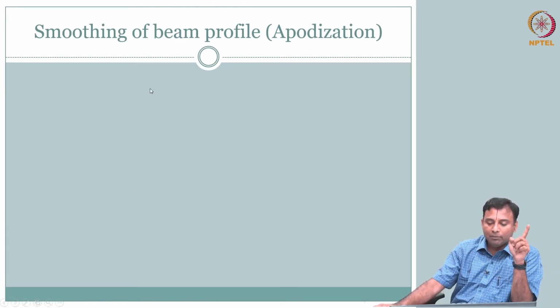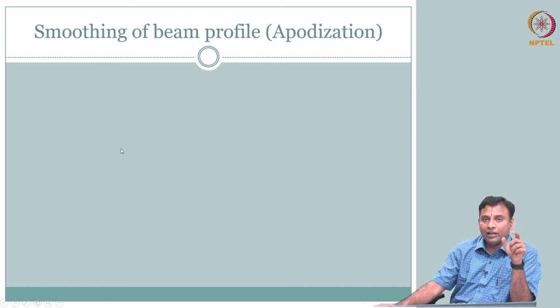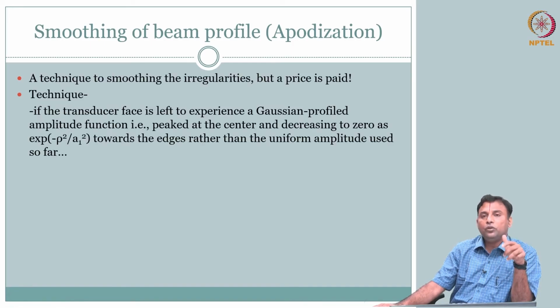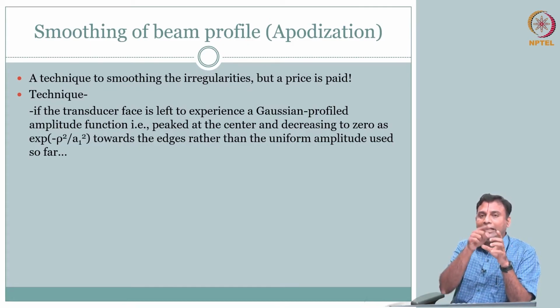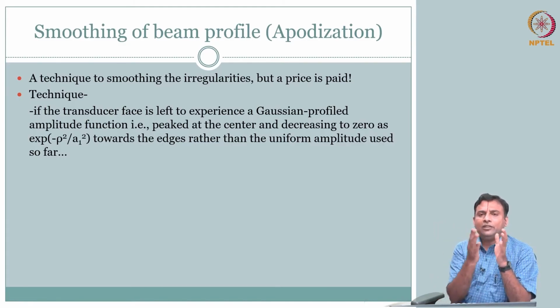Before we do that, let us just complete this beam profile that I was talking about, your rectangular function, hamming window. So you could do that here. So what we can do is have the crystal, but make sure that the crystal is not excited uniformly, you have some weighting. So the center point gets the maximum weighting. As you go towards the end, you have less weighting, and how much weighting you give can be determined based on your window function. Okay. So you could come up with a material. So basically this is sound. So I want only the center to contribute, sides to contribute less.